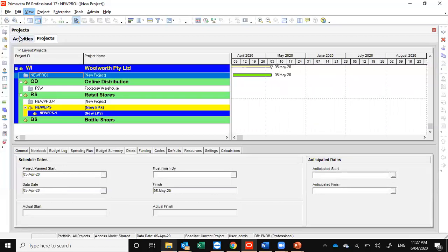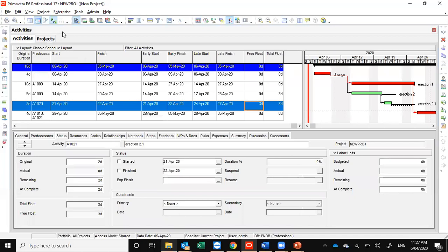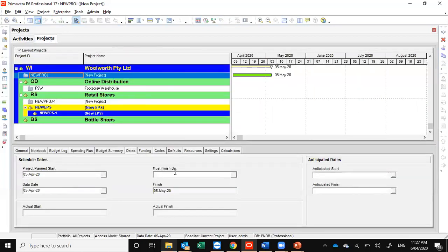Yes, thank you. As we discussed, mostly we have two levels of constraints. First is the project level. There is only one constraint at project level. While we are creating a project, it's good practice not to add a finish date, because once you plan in Primavera, it will show you the finish date based on the durations you're using. But somehow management will pressurize the team to complete the activities before the finish date, or before the planned finish given by Primavera.